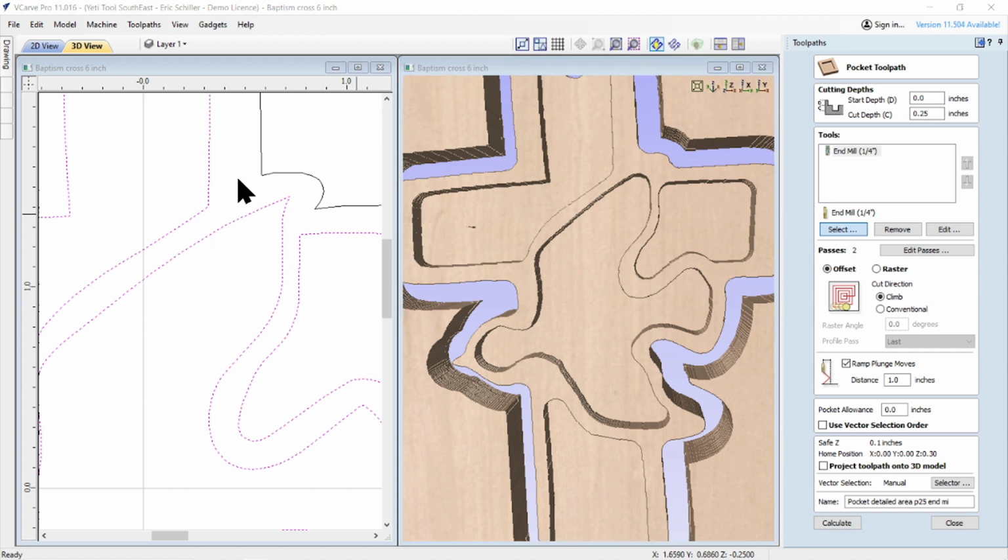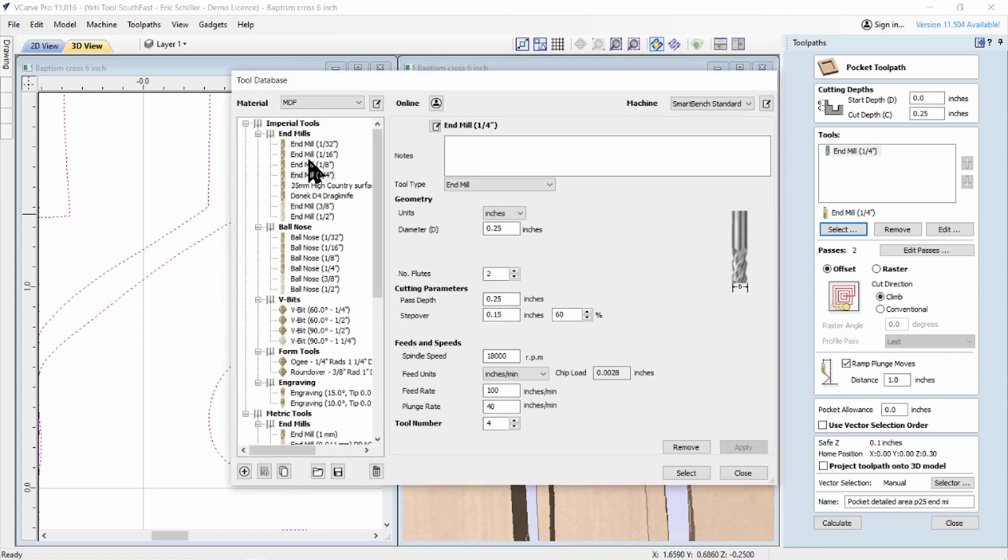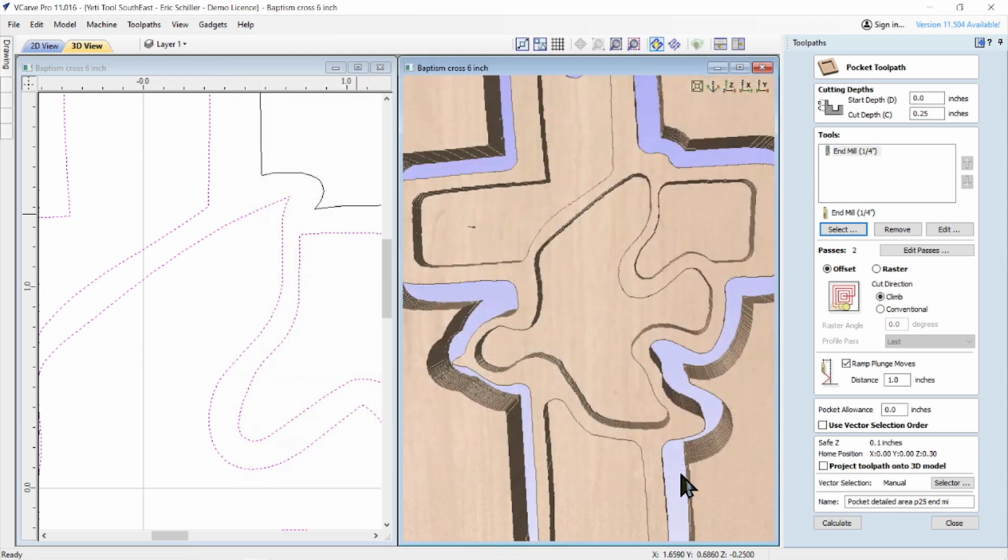and the same vector lines, same groups that we shift and added, and I'm going to come in with an 1/8 inch tool, and it's 60 inches per minute and 15. That's good. A 40% step over. It looks good, and I'll have it calculated.